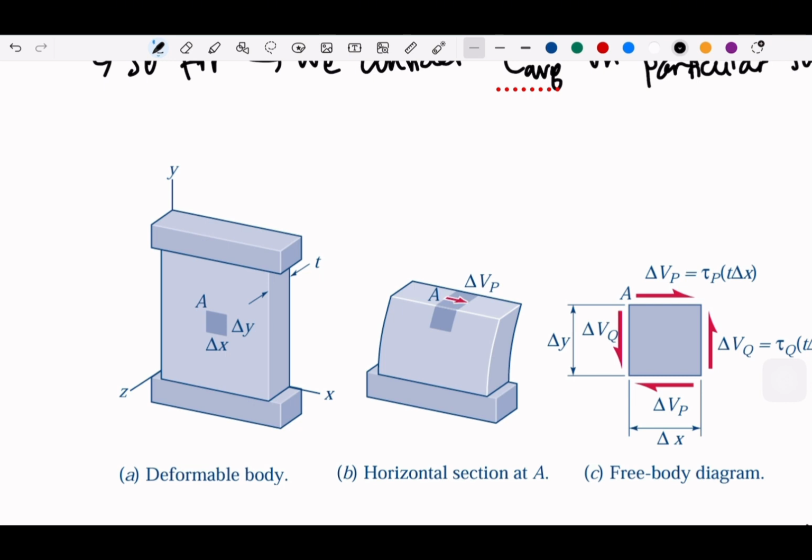So this is what the reality could be. So in practice, in design, for example, sometimes we only focus on the surface for the shear. So we only compute the shear assuming that it only works on the shear. Like when you have the lap joint with a bolt, we only think that the shear that is exerted is only on the surface of the bolt.